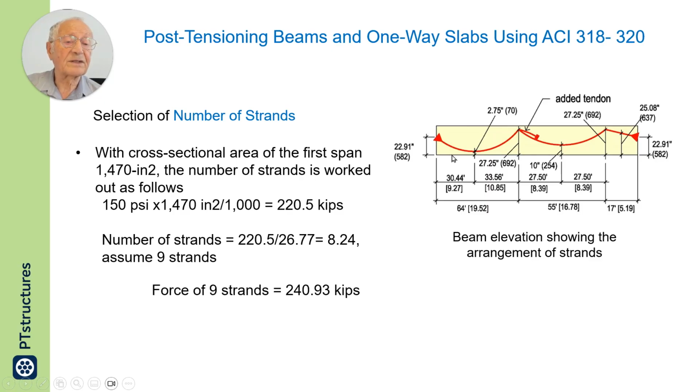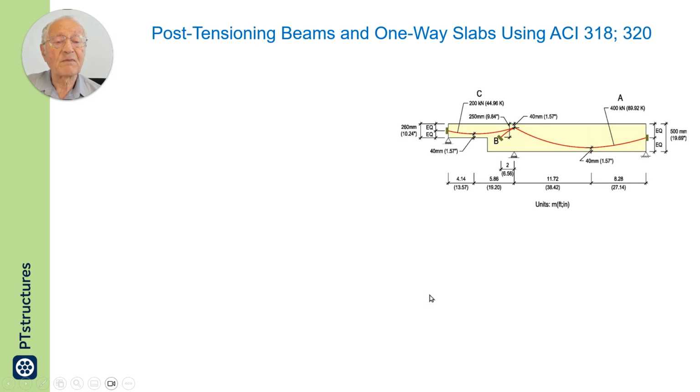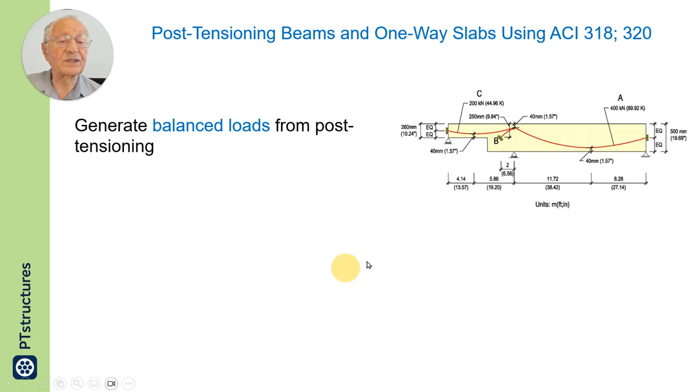With 9 strands, I form the arrangement of the tendons, knowing the position at the top, the position at the end, and also the high point.